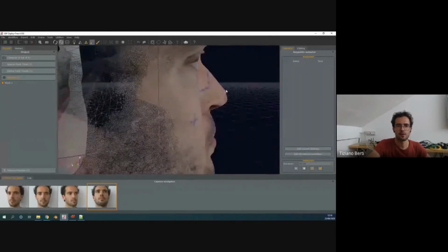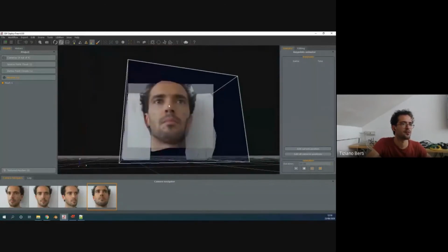So it's not done correctly. Probably because in those 4 photos there was some kind of defect. I can see that it's the point where there is a highlight. So again, a shiny object like my nose is not fine for photogrammetry. It's better if you cover your face with some fine dust, like the one for makeup, to make it less shiny if you want a very proper scan.